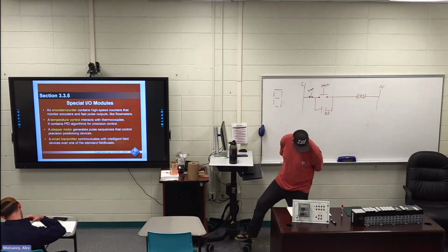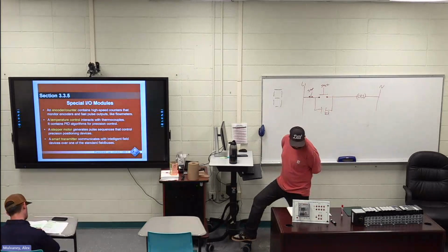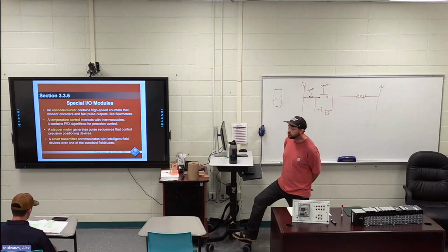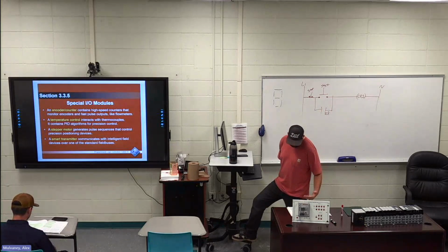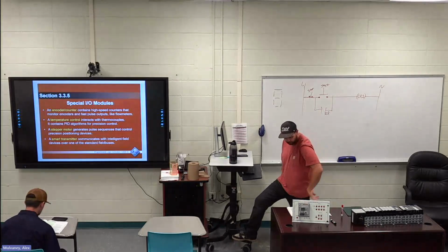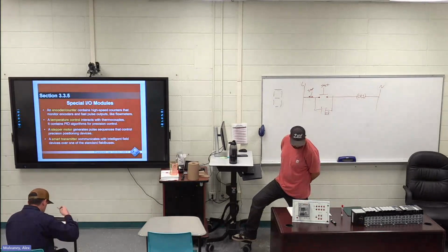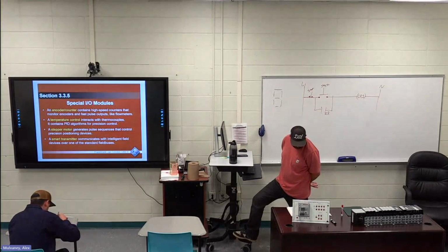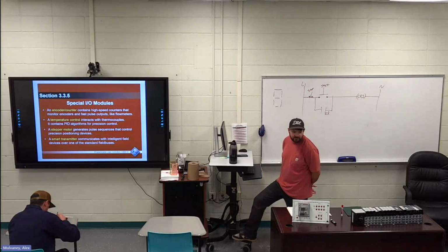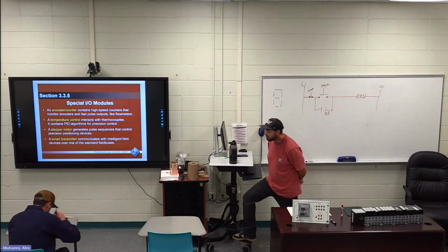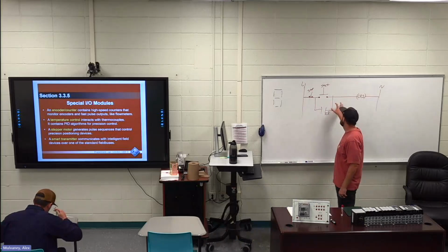Section 4, PLC programming. The language is going to be important. There are different languages that this stuff is written in. My first highlight is all 5 of those different languages: ladder diagram, function block diagram, sequential function chart, structured text, and instruction list. This is how a PLC talks.